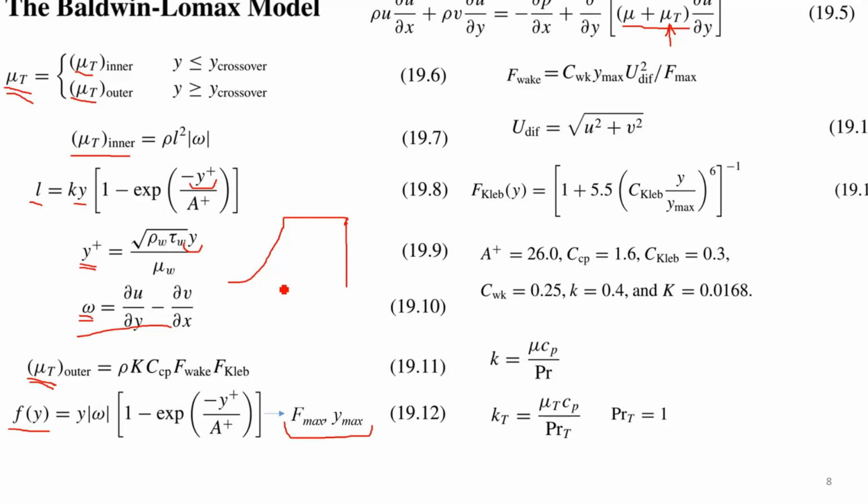And by this procedure, we define in each particular point in x and y coordinates the turbulent part of viscosity, and substitute it inside equation 5, and also we use it inside the energy equation because it consists also of a viscous part. And then solve. With this solution, we obtain flow with the boundary layer inside.